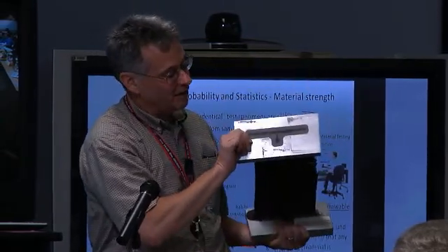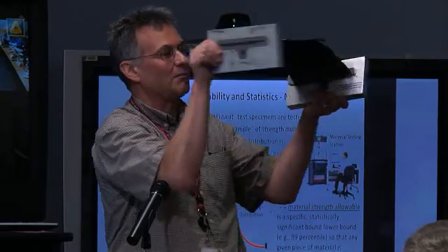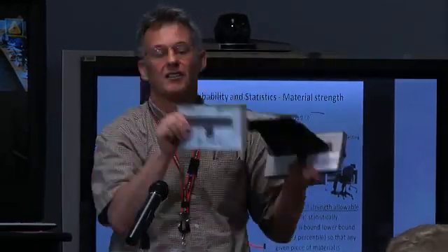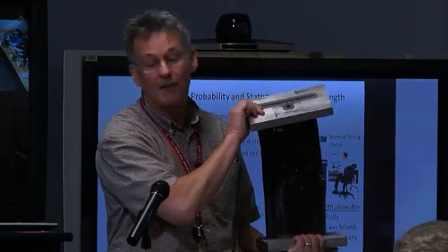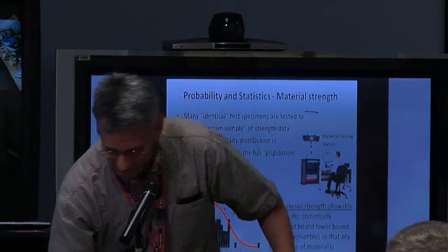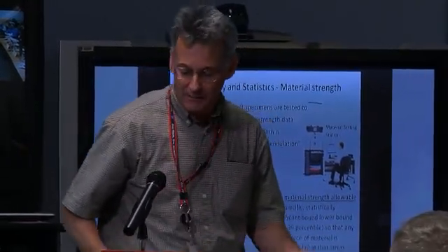And you essentially want to design the wing so it doesn't fail under load. In this case, this was a compression test. You see it failed. This is a composite design we're working on. This failed at about 50,000 pounds. This one little specimen. So right now, I guess the Boeing 787 is going to be the first large-scale composite airplane that flies, and it doesn't have this design, but this is a design that we're working on at Boeing that will be subsequent to the 787, we hope. But going from a simple material, you can go to a complex structure and use modeling and simulation to actually predict how that will fail based on these simple material properties.